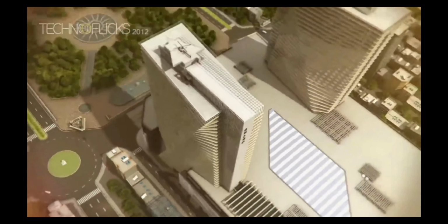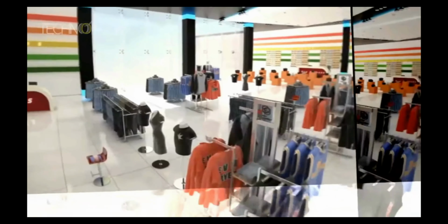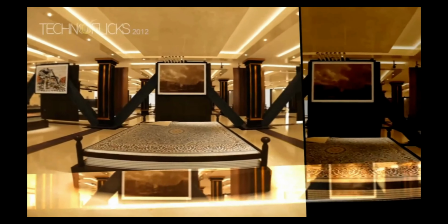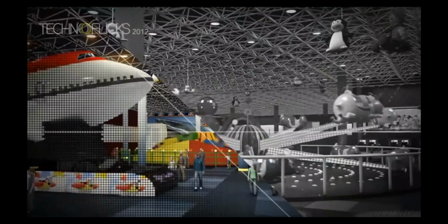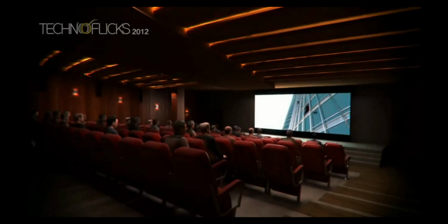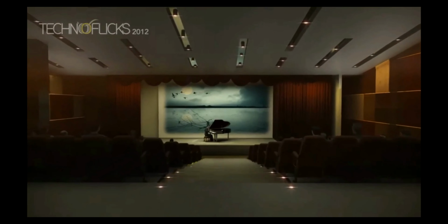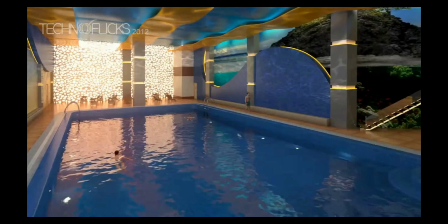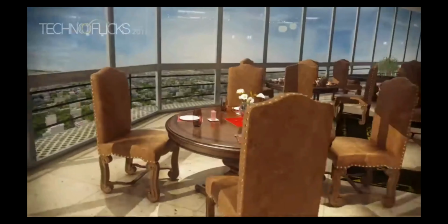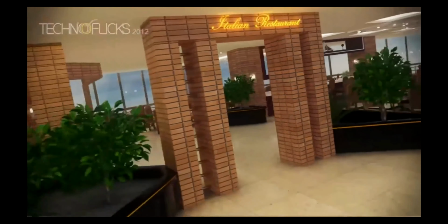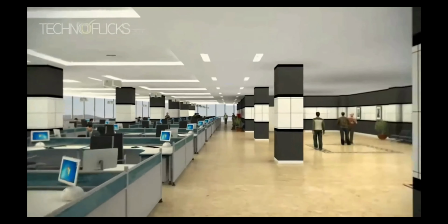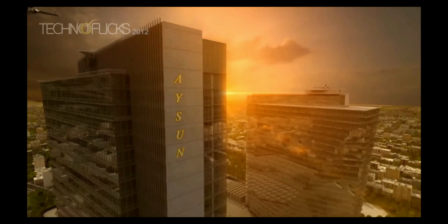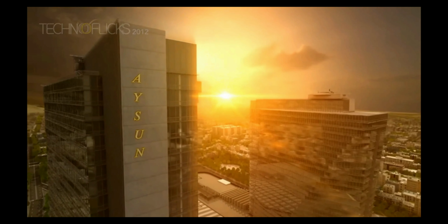This indicates that the scope of commercial buildings is wide, and there can be a lot of sources producing electromagnetic interference. Virtually all commercial buildings have areas with elevated AC magnetic fields, which are at the 60 Hz power frequency, that can cause interference problems with sensitive electronic equipment and may be of possible health concern when continuously occupied. These are unavoidable as they are caused by electrical distribution equipment such as transformers, distribution switchboards, distribution service panels, and distribution electrical feeders or conduits. Most commercial buildings have background fields in the range of 2 to 4 milligauss, but also have areas containing hotspots with much higher readings near these current sources.